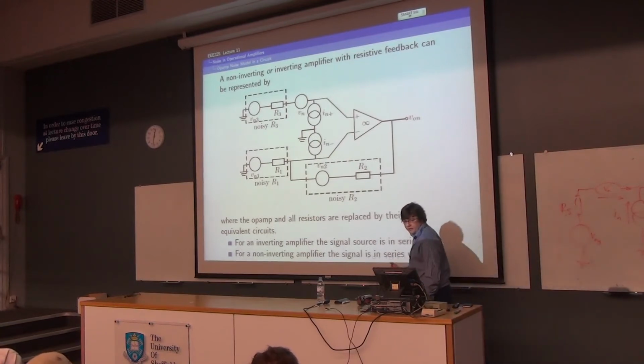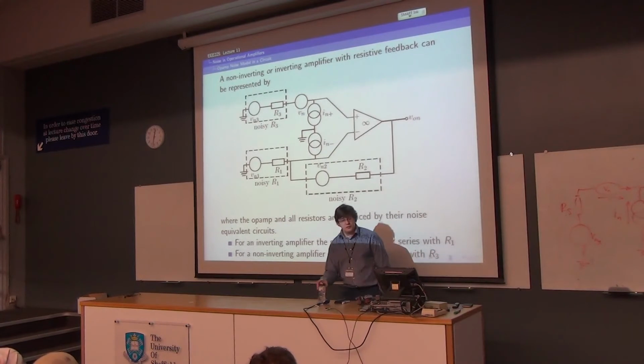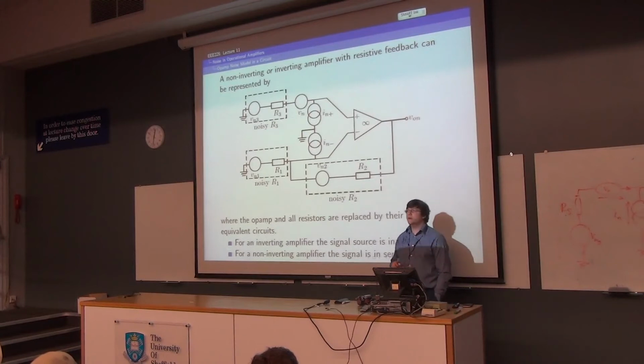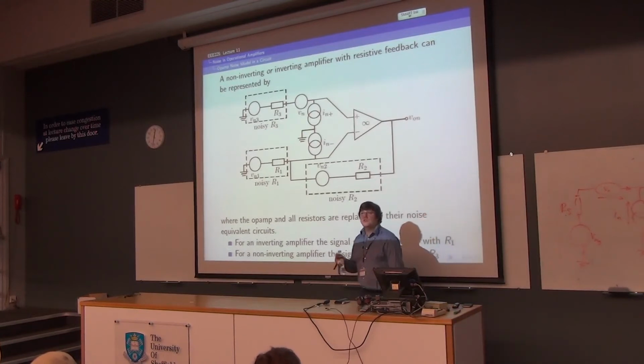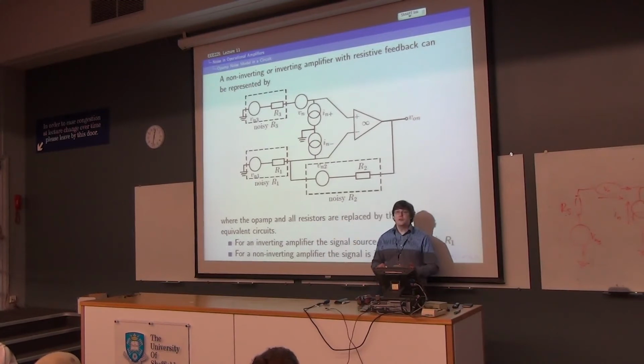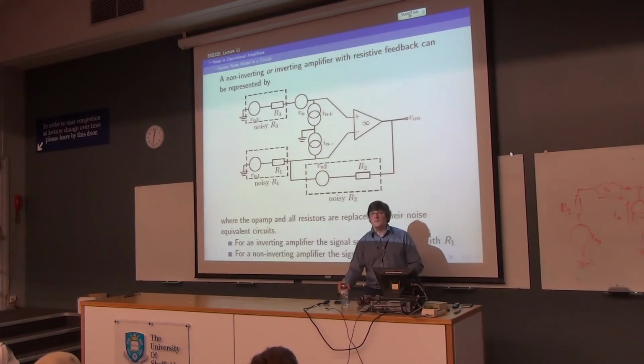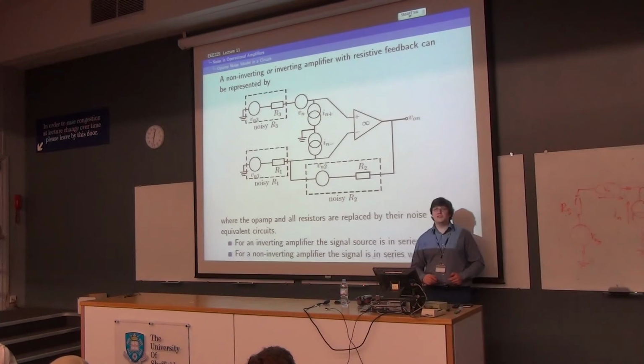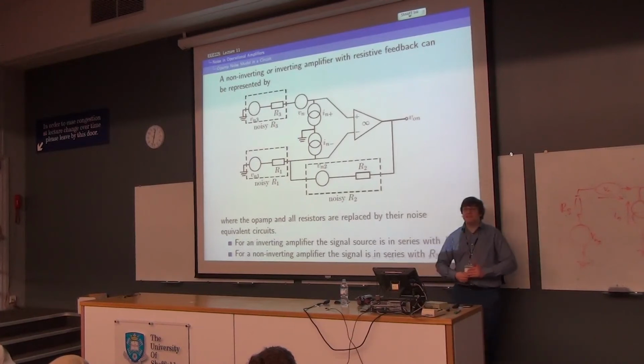Now I put R3 in because it generalises it, and also, if we were worried about other effects on the op-amp, like the amount of DC offset you get, putting in R3 can adjust your DC offset, and you might like to try and get it towards 0, although there is a bit of stuff to do with the choice of the op-amp as well. But this course doesn't contain DC offsets anymore, so let's just say R3 is there because it generalises the circuit. If you want to know about op-amp offsets, I've got some lovely notes on it, but it's not in the exam, so I have a sneaking suspicion there won't be a lot of interest.